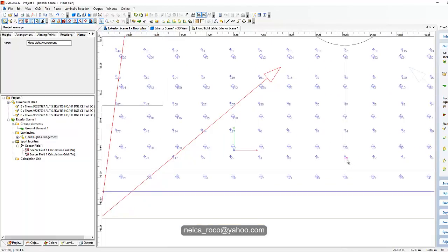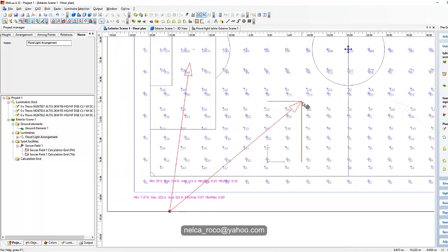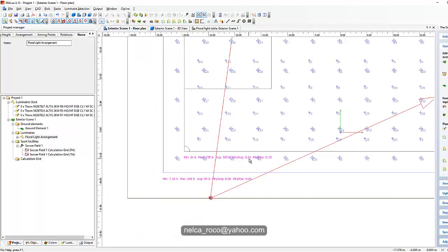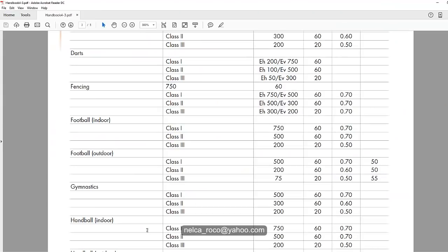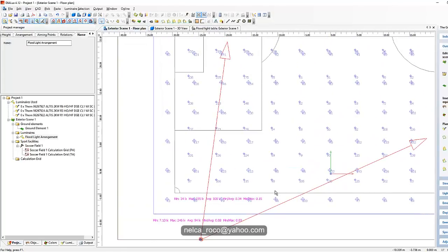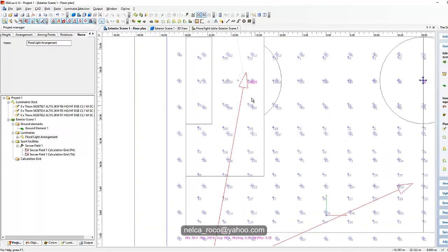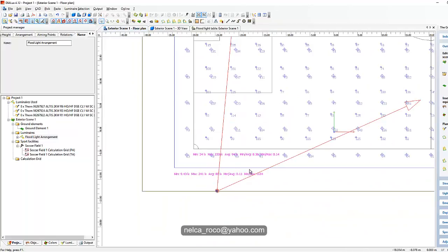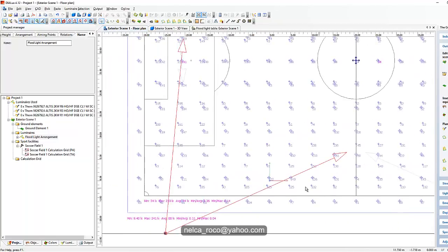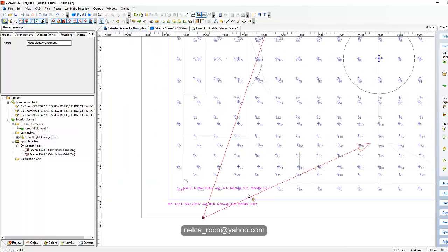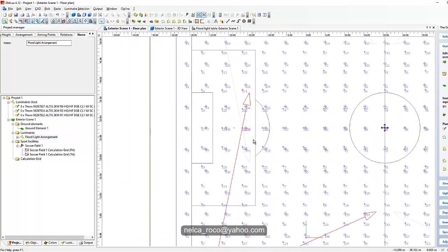And so now this is 25 lux, so we need to focus on this one, and then let's move it there. So you can see now that the uniformity changed. It becomes 0.34. It's great because our requirement is only 0.5. Okay? There you go, 0.5. And then we need to tilt it a little more there. So now it's 36 or maybe more. But be careful of keeping the floodlights too much aimed. Now it's not good. So let's make it there.